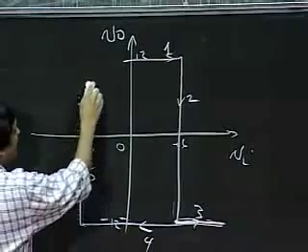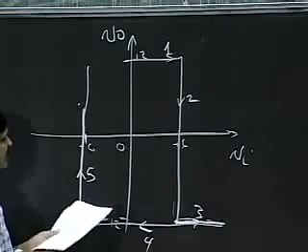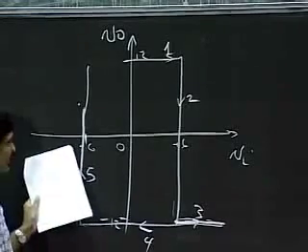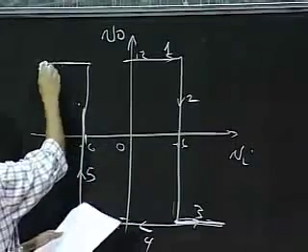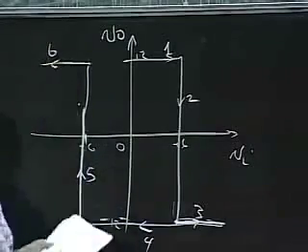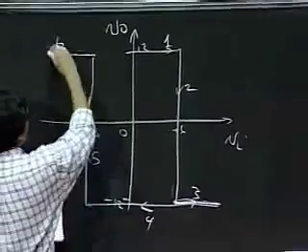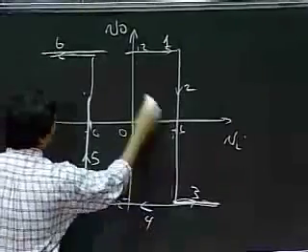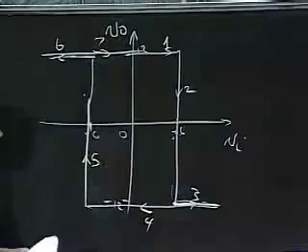I'm going up here, came up here, and nothing happens until I reach minus 6. But at minus 6, boom, I switch to the positive rail. And as I get more and more negative, I stay there. Then again, as I start increasing again, nothing happens until I reach plus 6. Think of that as your 7th step.